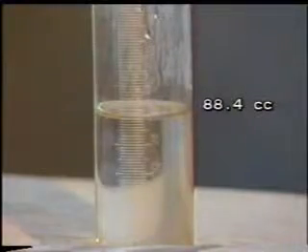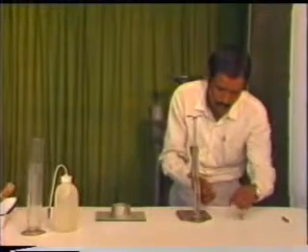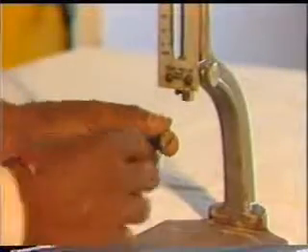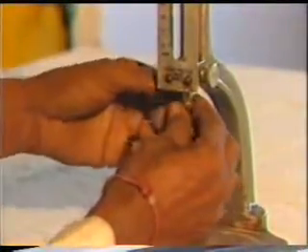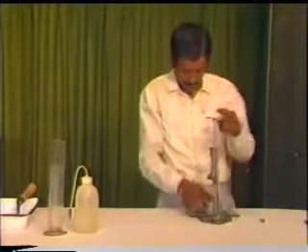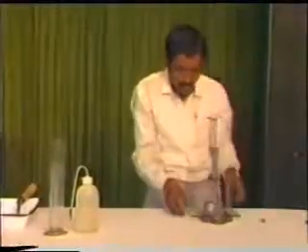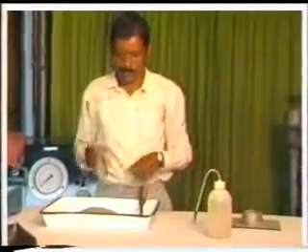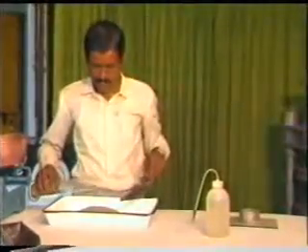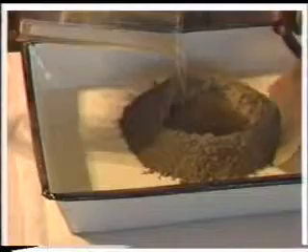Before making the paste of cement with water, fix the 1 millimeter square needle in the Vicat's apparatus. Adjust the indicator at the 0 mark when the needle just touches the glass plate. Lift the indicator and remove the mold. Mix the measured quantity of water with cement and simultaneously note down the time. Fill the Vicat's mold with the cement paste so prepared and level the surface.